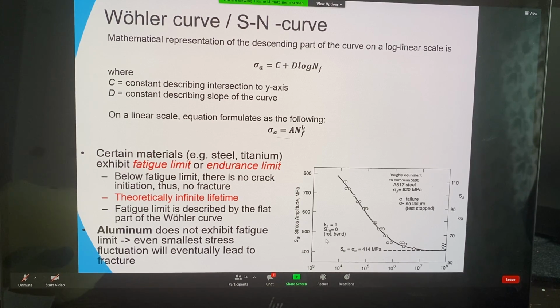And of course there you can understand easily that the effect of the higher stresses is more significant even with the lower number of cycles, because they stress the component, they stress the spring more than the lower levels. You can have more low-level stress amplitudes than you could have cycles of higher stress, of course.